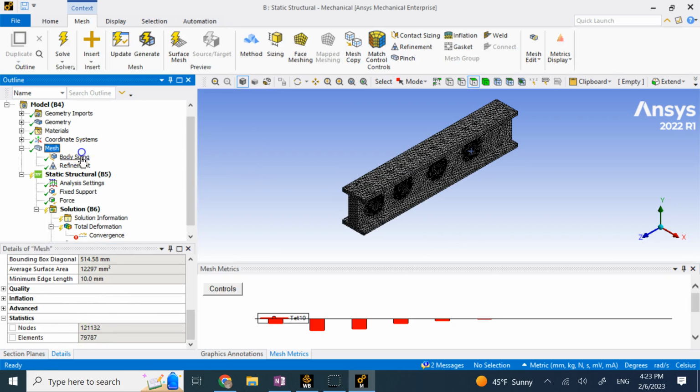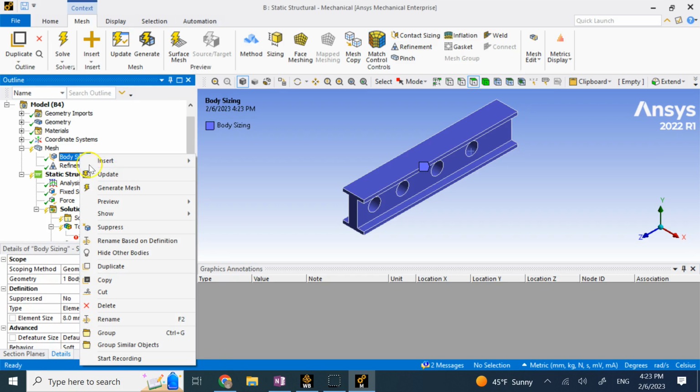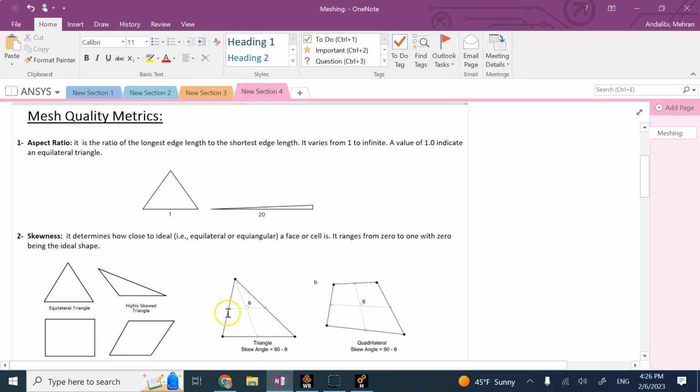So probably even maybe 8 mils would do the job in this case. And I don't need to go any further down. Yeah, you see here is about 59,000. So I'm very close, somewhere between 7 and 8, very close to 8 is probably where I can have my deformations converge up to 3 decimals. Okay, so this is the adaptive method.